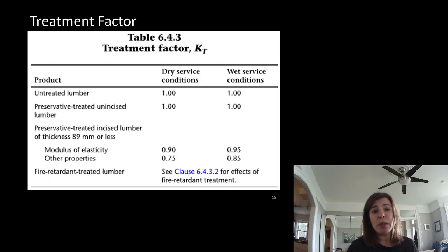Anyway, one of the things we did when we rebuilt it is we bought marine-grade pressure-treated lumber. So that anecdote, while it seemed completely random, talked about wet service conditions and how it can rot wood, and also marine-grade pressure treat. It was so heavy with the pressure-treated material that I could barely carry these pieces of wood. Now, they were 3x6s, so they were gigantic, and like 16 feet long, but I had a hard time moving them around and drilling through them, because we had to through bolt through them. I couldn't use an impact driver. I had to use an actual normal driver, which if it catches wrong will take your wrist along with it and break your wrist. It was like trying to drill through goo, and it would bind up all the time. So that pressure treating material is intense, especially the marine grade stuff.